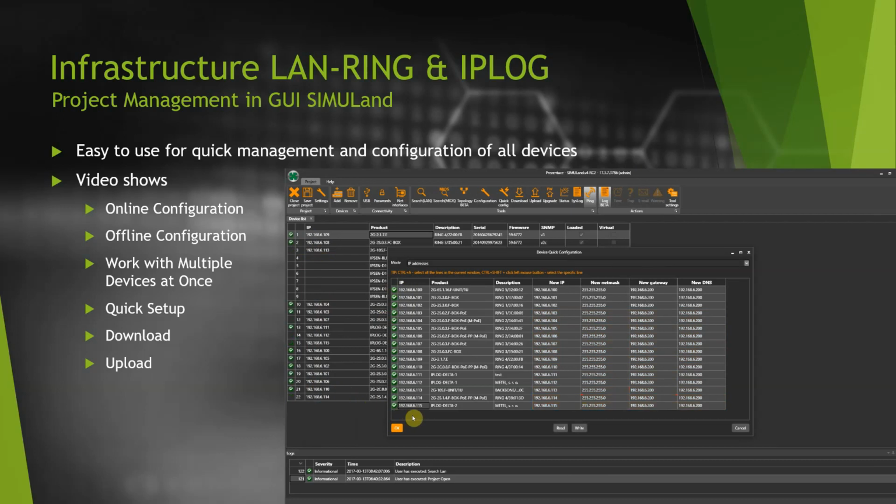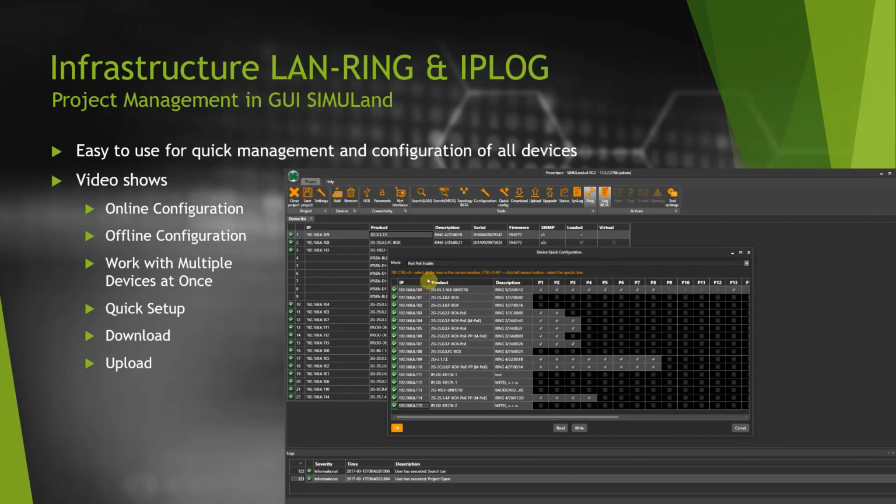By changing the mode from IP address to Port PoE Enable, the PoE configuration will be displayed. Ports that support PoE supply can have it enabled or disabled separately or by selecting multiple lines. The changes will occur on all devices identified within this column. Apply the changes by clicking the Write button.